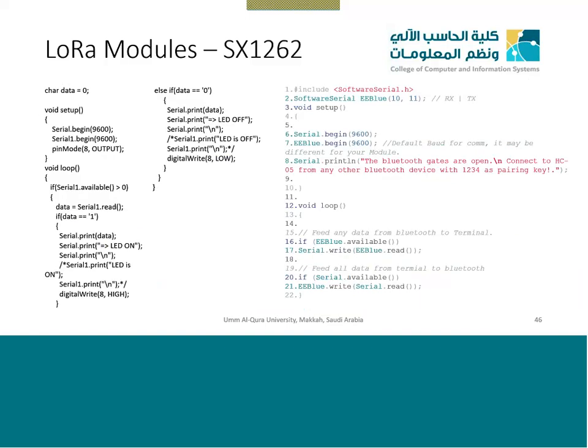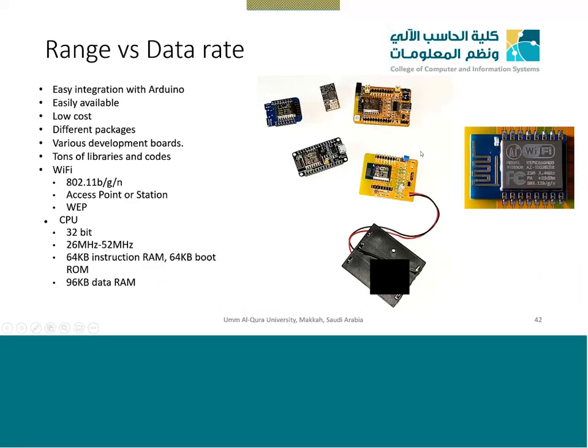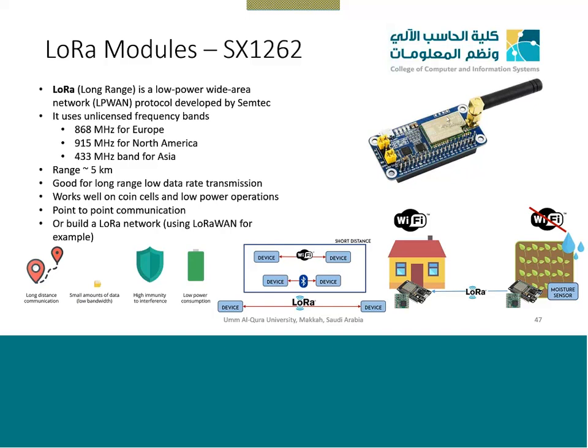If we talk about the 4G, 5G ones, we also have similar modules like these ones, but in that case, those modules will have a slot for the SIM card. We will put the SIM card in it, and then they will work. But the focus of our work is to use the non-licensed ones, so we will not take licenses, but we will need SIMs. For the SIM, there will be some financial package, the data package, and all these things, so that is an extra hassle. If you want the students to create low-cost setups or systems, or just give a concept of the system, Bluetooth, Wi-Fi, and LoRa are more than enough.